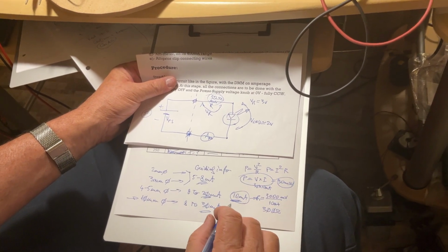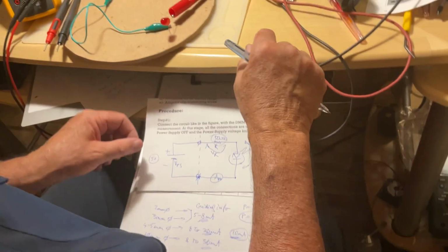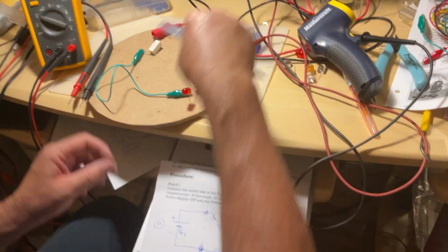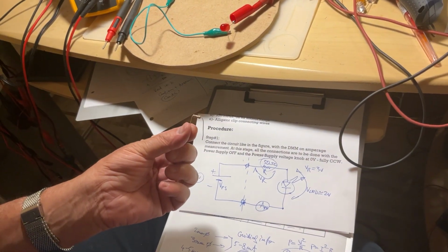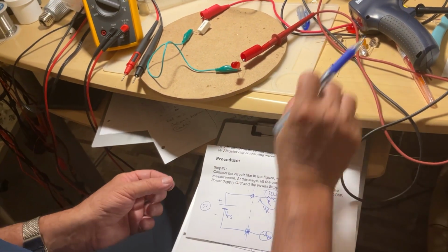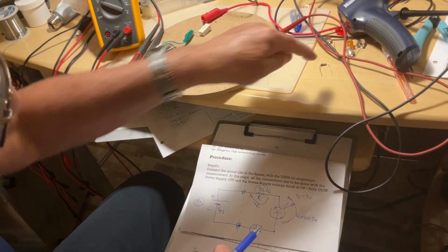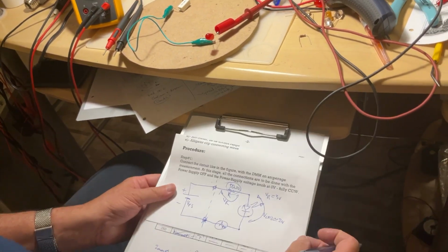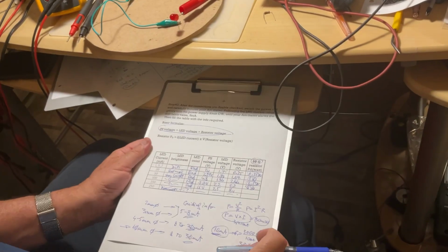So any small resistor you can buy, like if I pick up one small resistor from here, this is a half watt resistor. It is absolutely sufficient for the job. Okay, you don't need that huge one, a 5 watt. You just need this one. That's how you calculate it. Okay, so that was the use of knowing all these things measured in a testing circuit for a diode.